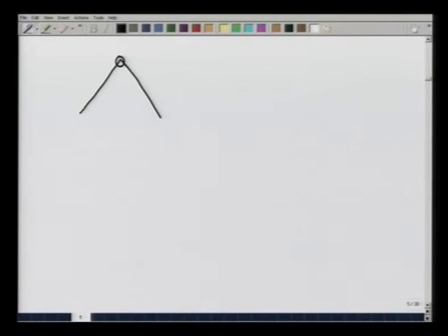For completeness, I should point out that the triangle that we just made should actually be fixed like this on a fixed pin on the left and on a roller or wheel on the right. This will make the system statically determinate. Through this, what I have done is provided you an example of solving for the forces in a truss through method of joints. That is, we take each joint, each pin at each joint to be in equilibrium.